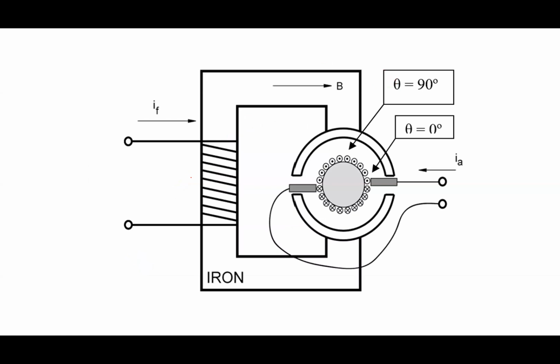And this is what a DC machine looks like in sort of an exploded view. And there are several different ways to make this thing. I've done it in the most general way, which is to say I've got two sets of windings. One of them here, this guy, is what I call a field winding. Just like we had a field winding in the synchronous machine, its job is simply to create a field, right? I could create a field different ways. One way to create a field would be magnets, okay? Like I just showed in that picture, right?